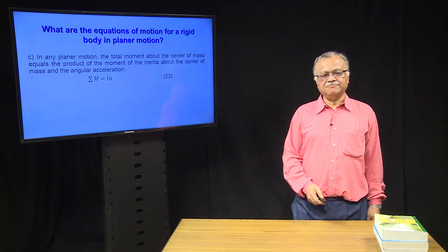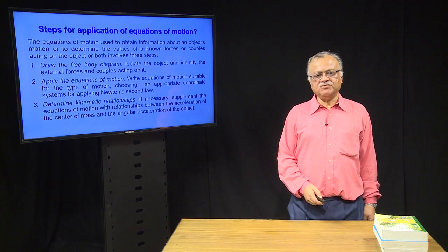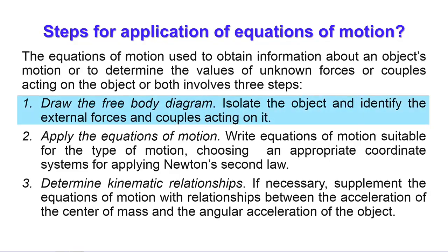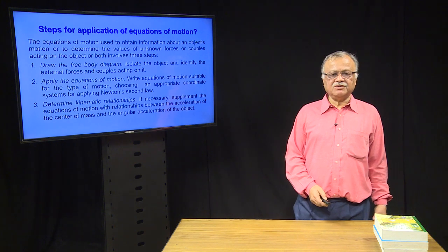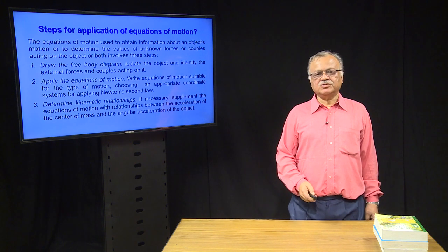With these equations of motion we can solve planar problems. Normally the steps we follow for solving any problem: first, draw the free body diagram. That means isolate the object and identify all the external forces and couples acting on it, because when you detach another body from this particular body, the effect is shown by these forces and moments.